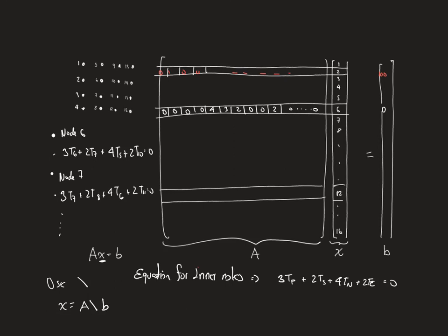In that moment, you will use a surface plot, contour plot, or pcolor plot, something that plots surfaces. You need 3 arguments: the x, the y, and the corresponding value. So I just typed it. This is the command to plot the results in MATLAB.